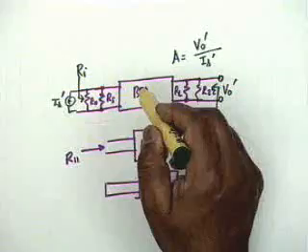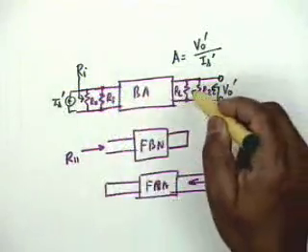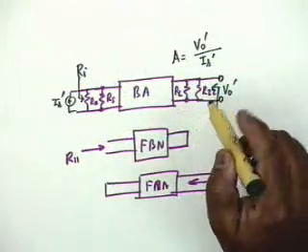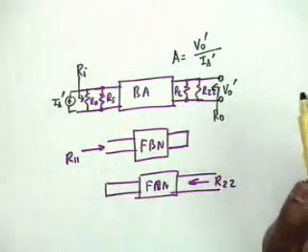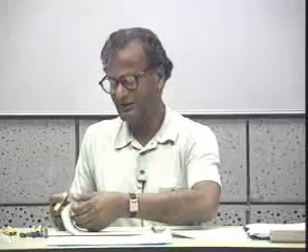And if I can now find the beta circuit and RIF and ROF, you have to take account of the fact that RIF will include Rs and ROF will include RL. You have to get rid of them. Alright? This is a caution one has to exercise. But let's look at the beta network. From the beta network, what do you want? Do you want a current or a voltage? Voltage. No. I want a current because it's a shunt-shunt comparison.